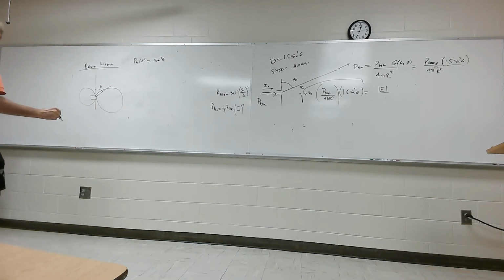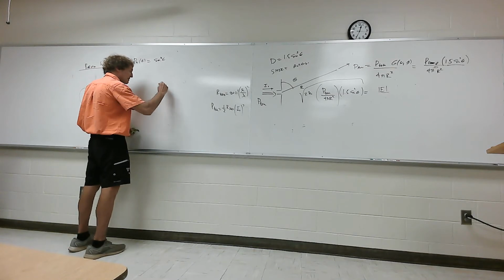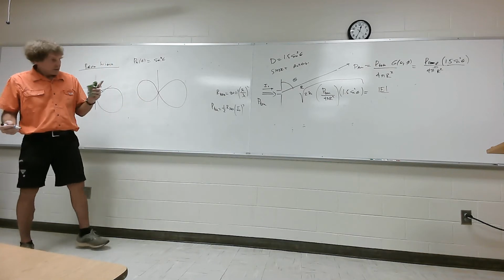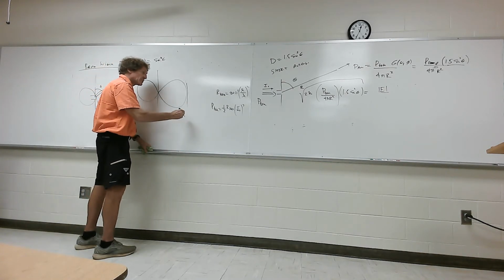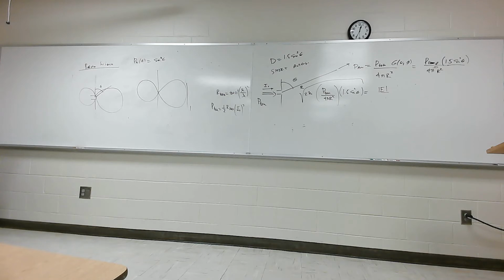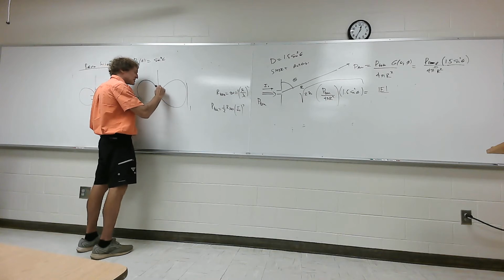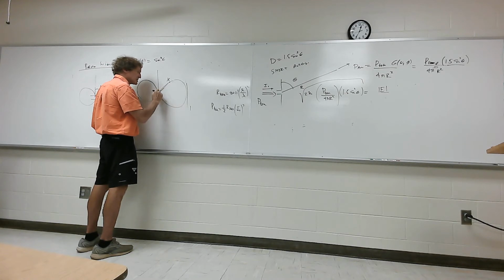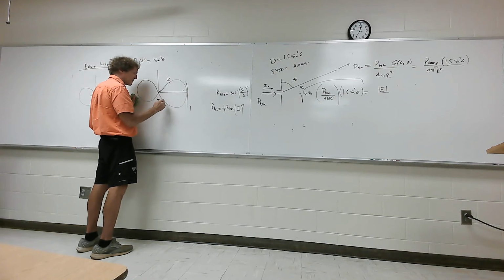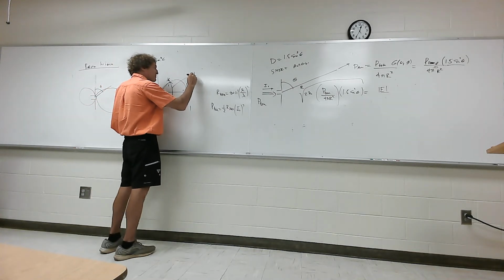Really what you're seeing is something that looks like a bow tie, like this. It'll be symmetric about the z-axis. So the normalized power pattern at 90 degrees would be 1. Y'all follow me? If it's normalized, the biggest value you can have is 1. The place where the power pattern goes to 1/2, remember, this length here would be 1, and this would be the power down to half. This is called a half power beam width.